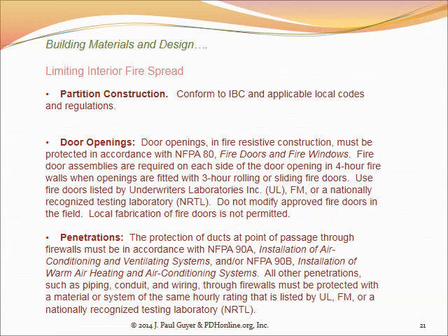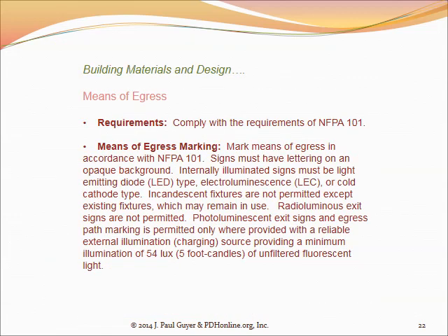Means of egress, again, the fundamental principle that you want to get the people out of the building. Well, this is where the exit signs and so on and the alarms that go off come into play. And these are dictated primarily by NFPA 101, the Life Safety Code. And that dictates where the exit signs need to be located, how they need to be illuminated, and then in recent decades there has been an awareness developed that some occupants of the building may be handicapped.